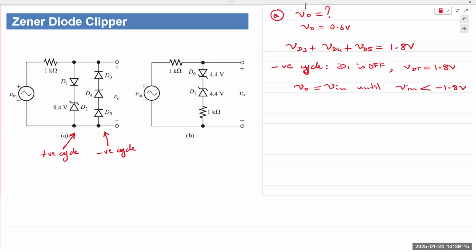That's all. The path follows a similar structure to the previous example. Yes. So I was assuming that the individual single diode voltage drop is 0.6 volts. So 3 diodes together would give us 1.8. If you assume 0.7, you would get 2.1. If it's given, we simply take that. If it's not, you assume whatever you wish. Right? You make an assumption. I assume a 0.6 volt diode drop and just run with it. So let's take a pause before I get to the positive half cycle.